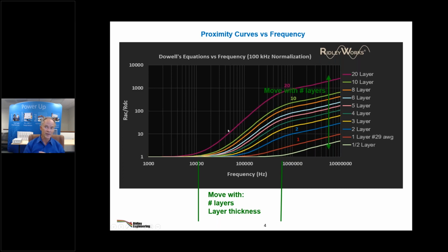So now you've got difficult decisions to make about whether to layer my windings this way or that way, whether to use foil or wire or bifilar, and so on. That's all the tools you have for manipulating these curves. We're going to see some specific cases coming up soon. Okay. You flag me, John, if there's more questions I should catch.